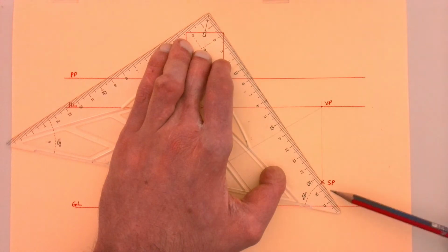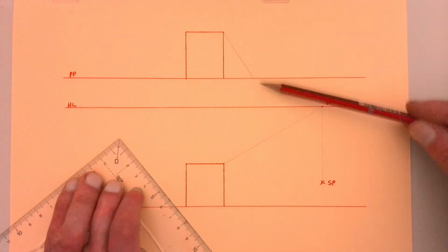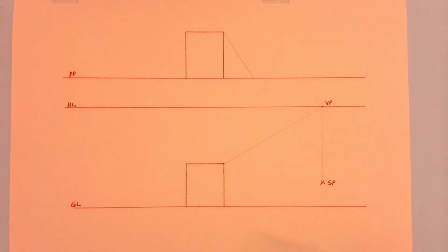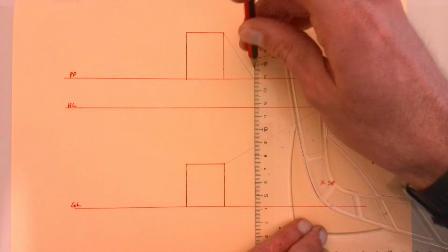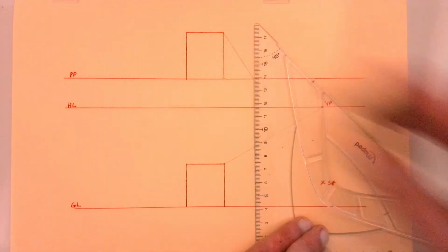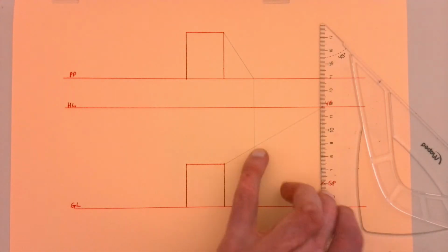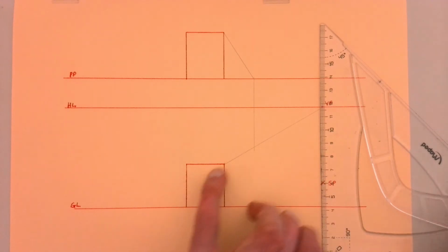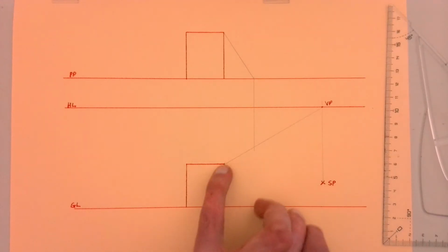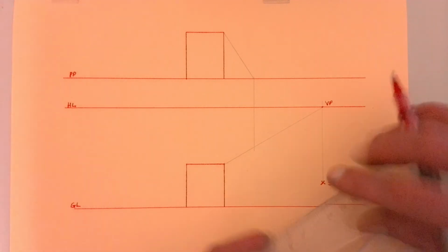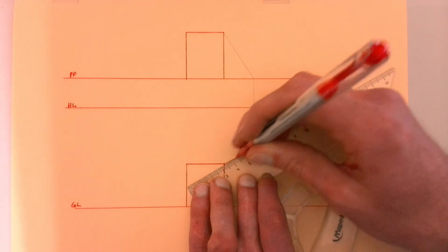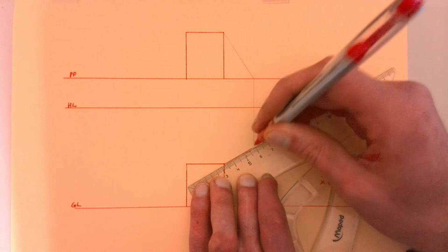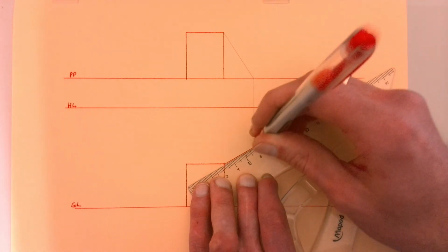If you do that with all of them, then the lines start to get a bit confusing. So we draw it just up until it hits our picture plane, and where it hits our picture plane, we then draw a construction line from that point straight down, and where that meets up with the line we drew out from that corner, that tells us where that line is supposed to end. So we can draw that line in dark, because we know that that is now the ending point of that line.